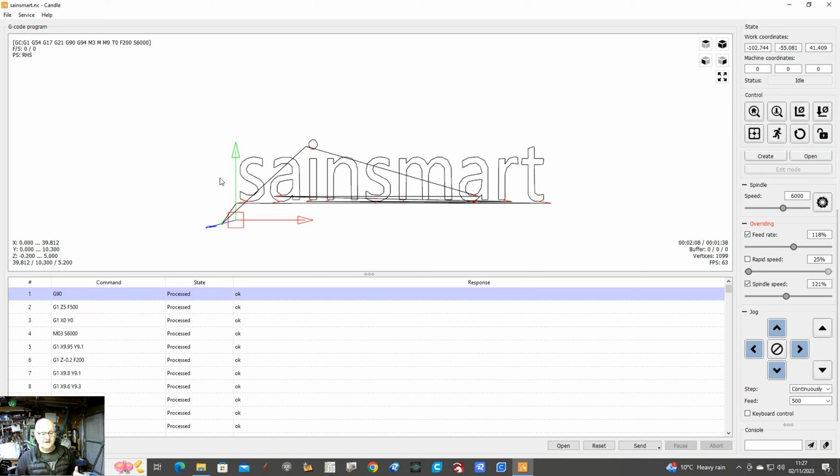I did have an issue where I didn't realise I'd left the offline controller connected, and when I came to send the machine, it was a click to move the Y-axis plus, which is away from the home position, and it just carried on, and I thought, what's wrong with this? All I did was power off, disconnect the offline controller, connect the USB again, power back on, home the machine, and it worked fine.